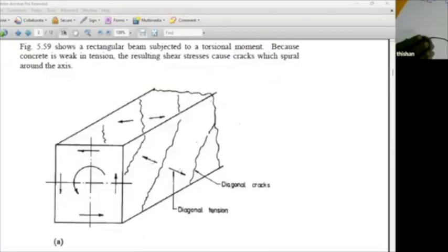The moment you look at the diagram, you can see why we need cross links, because torsion is everywhere. So you can't have any weak corner. So in the shear link, where we lap is a weak corner. But for torsion, we can't do any of those things. So that's why we go for the close link.